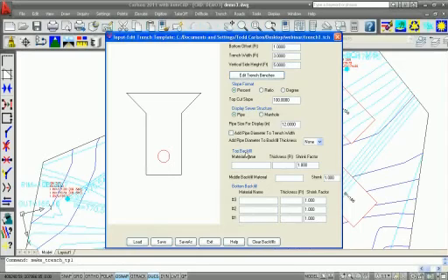So what's new here is we now have a top backfill and a middle backfill. So say I knew at the top of my trench I wanted a foot of gravel, I can now define that. Okay? Before, we only had the 3 bottom ones. You couldn't define a top surface for that as the surface fluctuates. Let's still define some bottom ones. Say bedding 1 at a foot and bedding 2, and I'm going to put this at 0.01, and I'll show why in a minute. And then a top, let's call it stone, of half a foot. Okay? So we have a bottom bedding, middle bedding defined, which is 0.01, and then stone at half a foot.